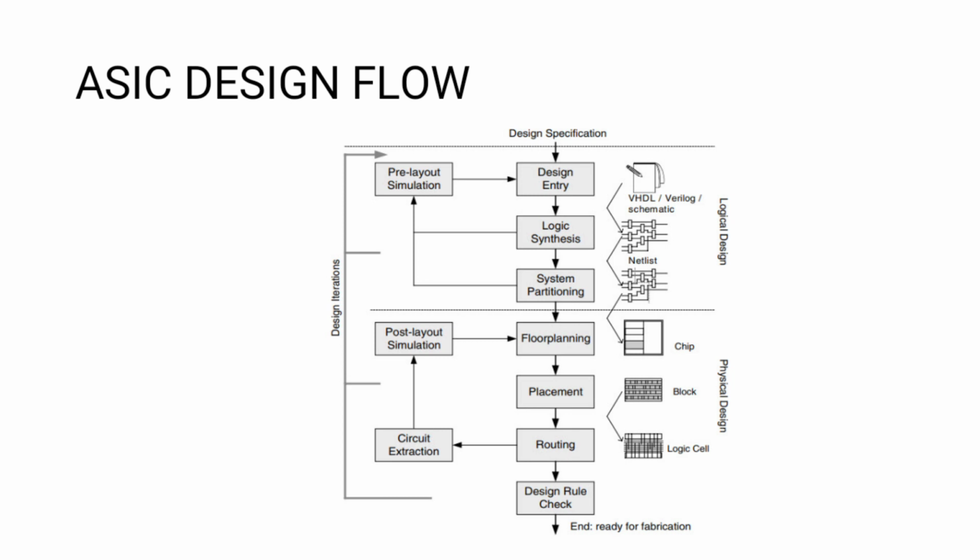After the simulation is done, we go for logic synthesis. Logic synthesis deals with your digital hardware. Whatever programs you have written in Verilog or VHDL must be converted into digital logic in terms of slices, flip-flops, registers, logic gates and multiplexers. So whatever logic you have written in Verilog, the corresponding digital hardware must be present in the netlist after the synthesis process. Once the netlist is created, we have an idea about what digital hardware is available. Then it should be partitioned.